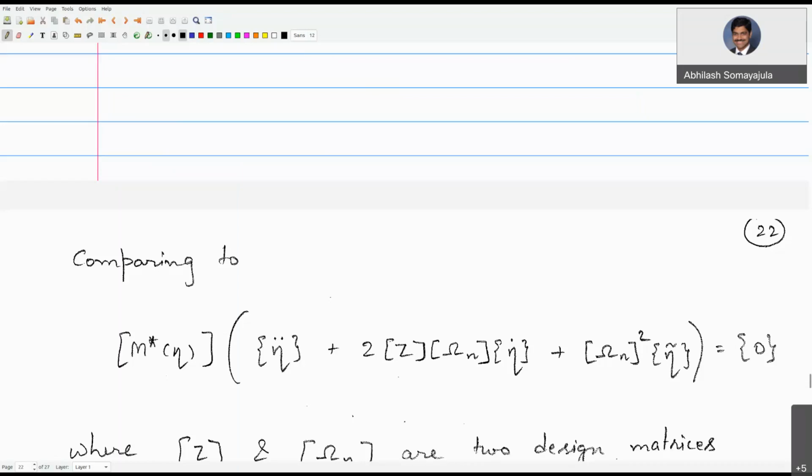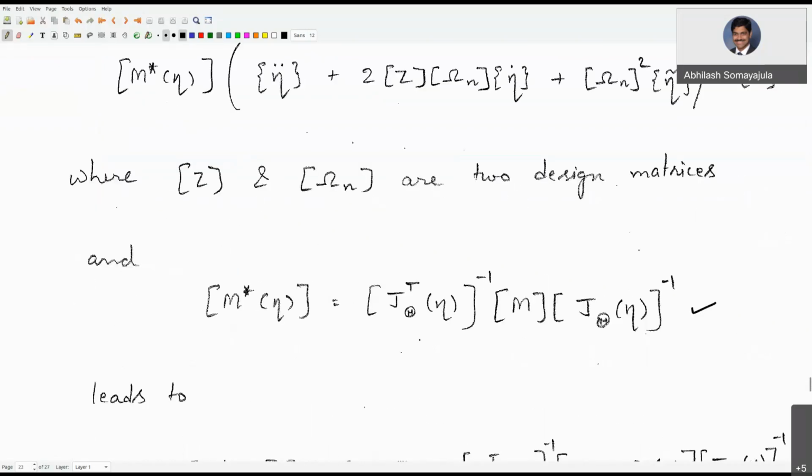So to answer your question aptly, your PID probably will not be used there. You will require much stronger, nonlinear control laws in order to make those maneuvers happen. They definitely are not using typical PID controllers. You can't achieve that. Good thought process though, good question.